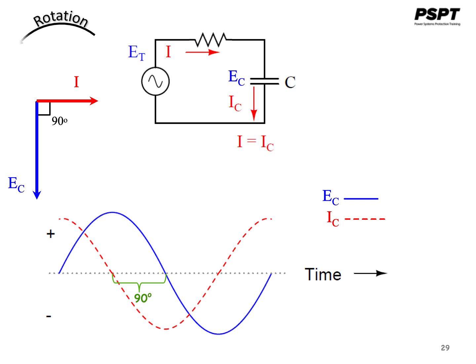The phasors would look like this. The capacitor voltage lags the circuit current by 90 degrees, or you might say the current leads the capacitor voltage by 90 degrees. I have also shown the voltage drop across the resistor, which is in phase with the current, of course.